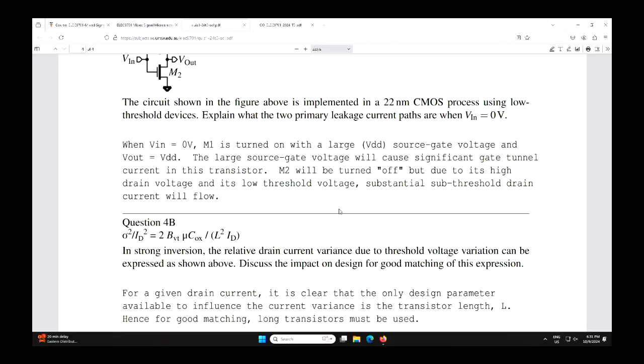Maybe what you're designing is a system on a chip, and 90%, 95% of the chip is just digital. So that will drive what technology you're choosing. And then your interface circuit just has to cope with being designed in a 22 nanometer process. It's not optimal for what you designed, but that's what you got to live with. It is a very common situation because if you look at systems on chip, most of it is digital, but not all of it.